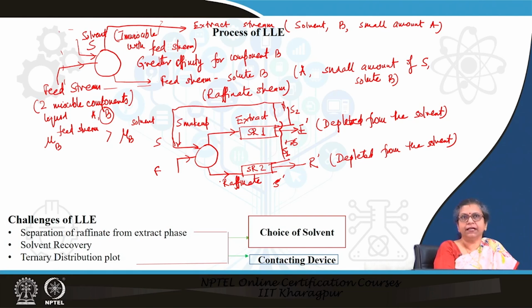In fact, I will tell you one thing, you will often find that the efficiency of the process is quite low. Normally we take 50%, maybe maximum 70% efficiency, much less than the tray efficiency that we get for distillation processes. Remember one thing, this reduced efficiency is mainly due to the insufficient separation between the extract and raffinate phases rather than the equilibrium considerations. This is something which we need to remember in liquid-liquid extraction processes.